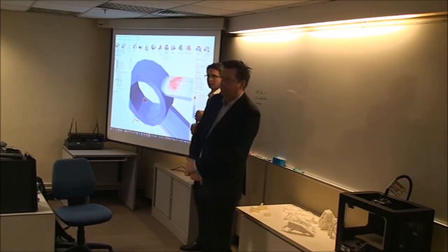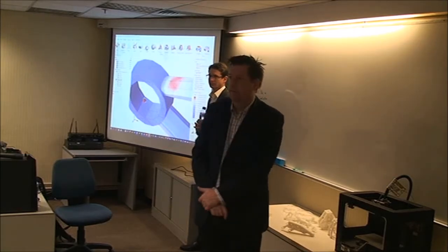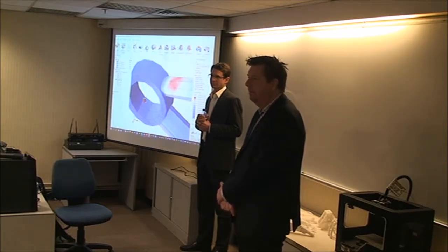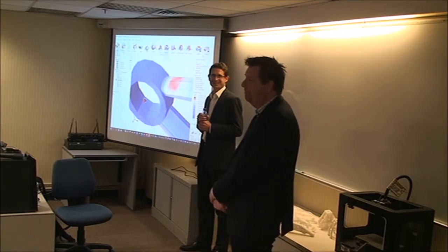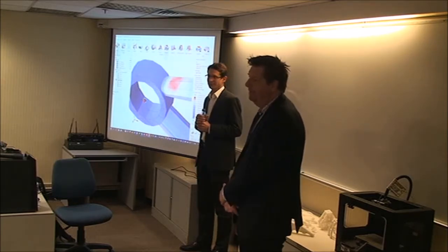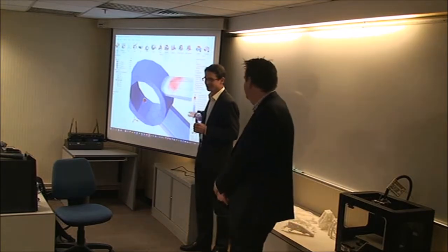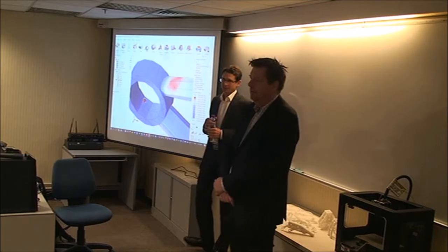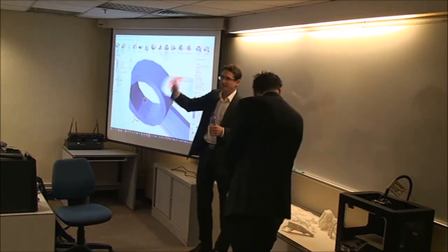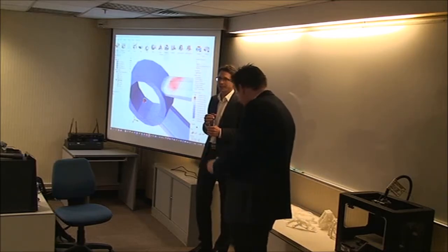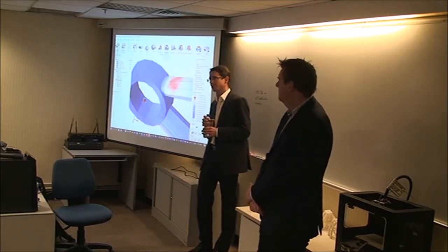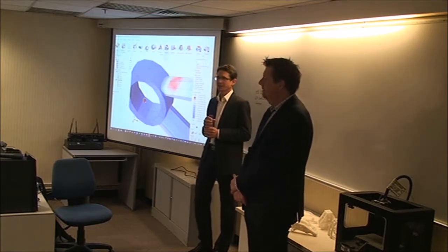Sorry, did you mention that the capability of this component will also depend on the direction of printing? Yes. The directional printing and the heat treatment, it's all in there. That's why I had it in my slide: just to buy a printer and start printing is not yet the end of the story. That's why, for example, the Airbus guys put all the effort and investment into understanding what is finally influencing the behavior: printing direction, material properties, material treatment, before printing, after printing, and so on.